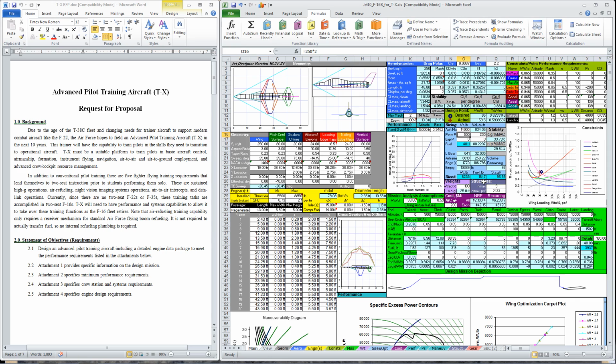And that's pretty close. We're really having trouble making that maximum Mach at this point. So let's guess that the wing is a little too big. Again, let's try 220. And now we're making the max Mach. We're kind of sitting right in the armpit, if you will, of the two constraints, the max Mach constraint and the sustained turn constraint.